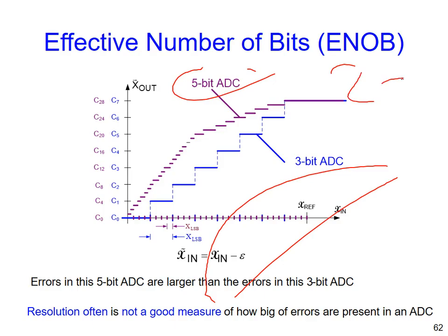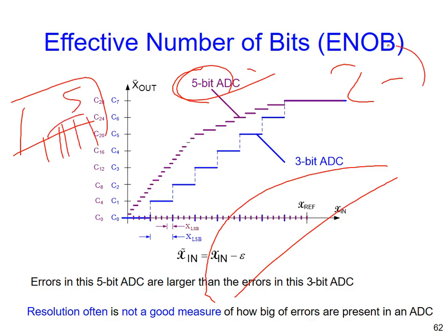You will be curious, you will be furious, very angry. So you will say, hey, there is one way. For example, for such a 5-bit ADC, you can omit the last one. After packaging, from the beginning, you have 5 bits. But after measurement, wow, you have only 2 bits in linearity, effectively.